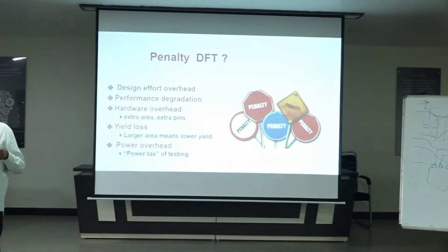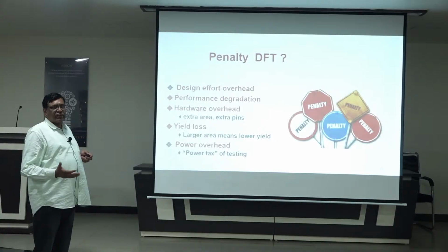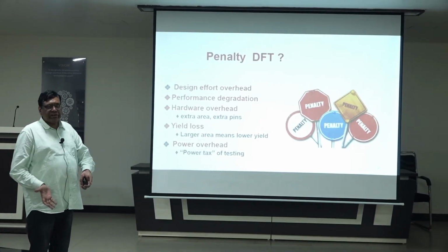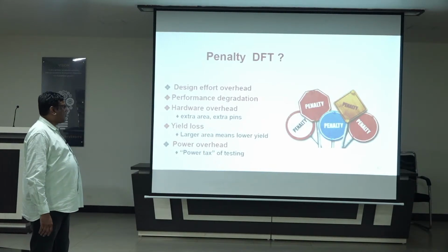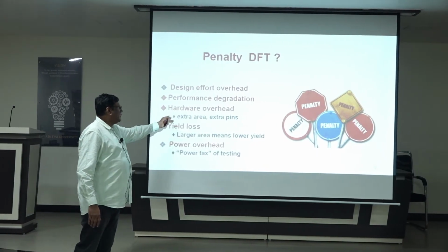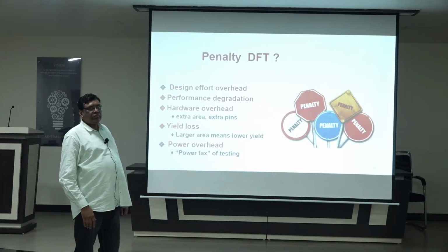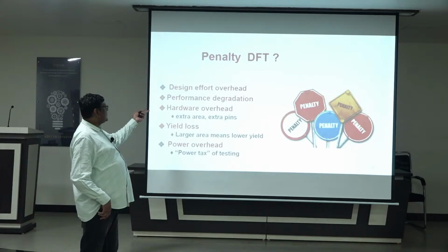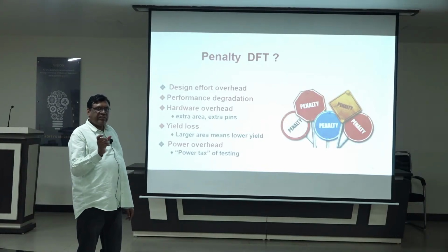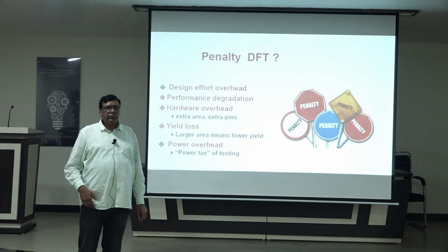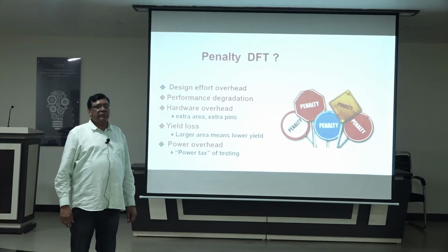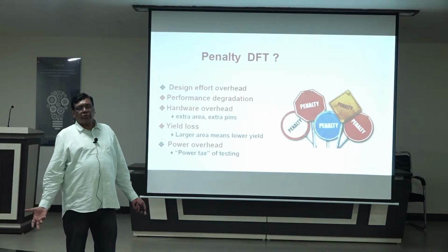There will be a penalty of DFT. Already we discussed that 30% overhead will be there. Along with the design we have to provide DFT. So that overhead is a cost: hardware overhead, extra area, extra pins, and performance degradation. Because of DFT, chip speed may reduce slightly. Impact on the speed will also be there. But we have to do it.